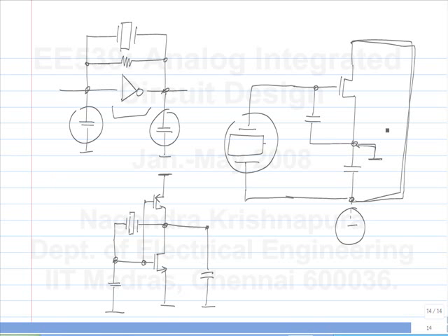So that's the usefulness of the negative resistance, but when you are trying to make an amplifier, it's a problem. We also found out how to compensate that problem, because we could split the impedance into a parallel combination of a capacitor and another branch which has a negative capacitance and a negative resistance. If we put the same series combination of the same capacitance and resistance but positive ones, we'll cancel it off and we'll be left with only the input capacitance of the circuit. That will stabilize the amplifier.